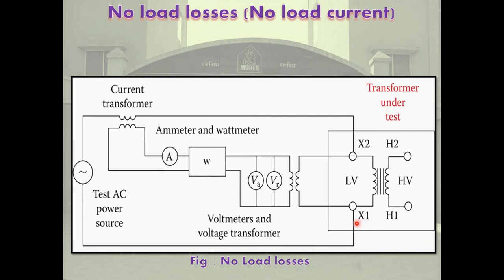The defects in magnetic circuit of the transformer cause an increase in the no load current and losses, and hence reduce the efficiency of the transformer and may lead to excessive overheating and a reduction in lifespan. To check the transformer for such defects, its no load or exciting current and losses are measured and compared with the design data. For this purpose, the no load loss and exciting current measurement are carried out.